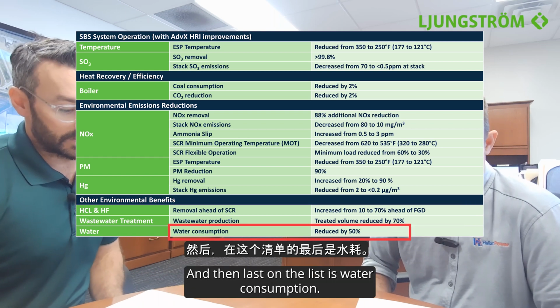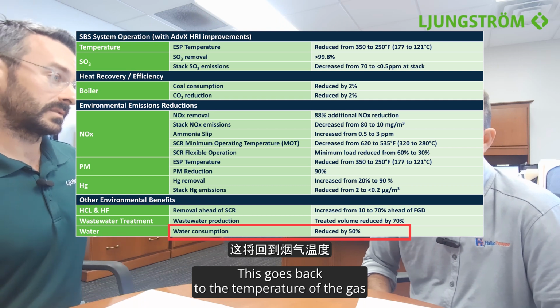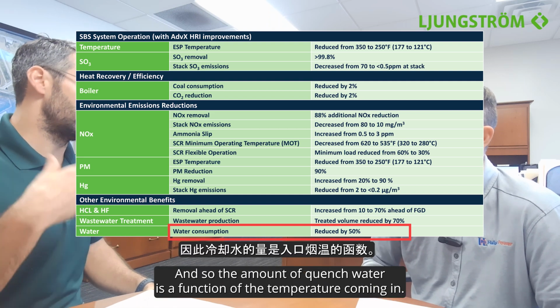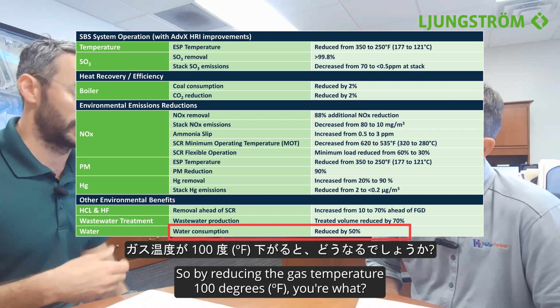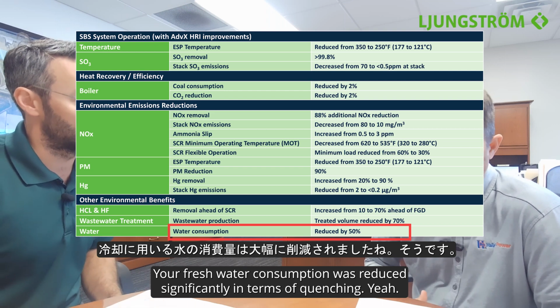And then last on the list is water consumption. This goes back to the temperature of the gas going through the precipitator. So with a wet scrubber, you have to quench that gas. And so the amount of quench water is a function of the temperature coming in. So by reducing the gas temperature 100 degrees, your freshwater consumption was reduced significantly in terms of quenching. Yep.